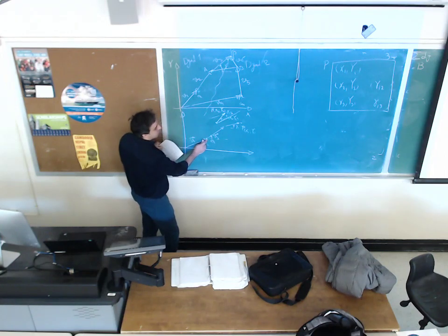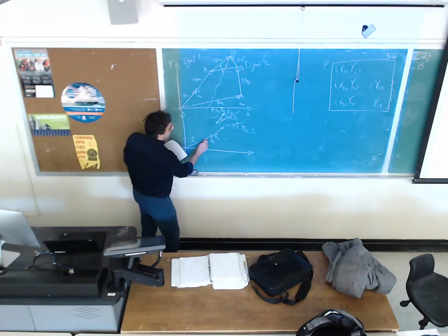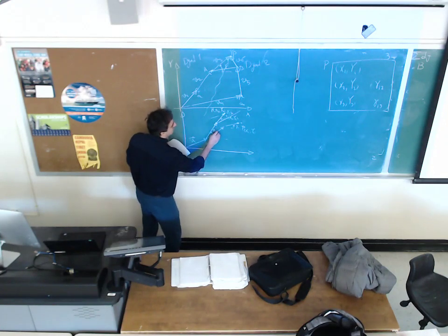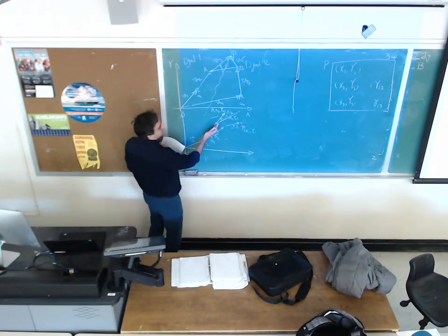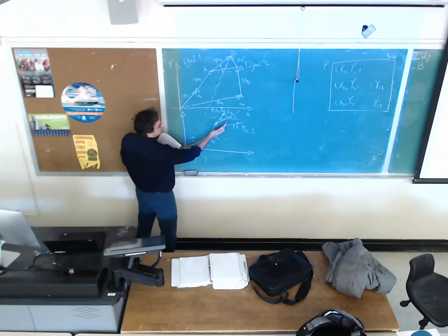The location of O2 is not going to change, but this link is going to rotate to this position, and this angle is going to be theta 1,2. It's rotating from the first precision point to the second precision point. Do the same thing for the third precision point. It's going to rotate, for example, by the angle of theta 1,3.